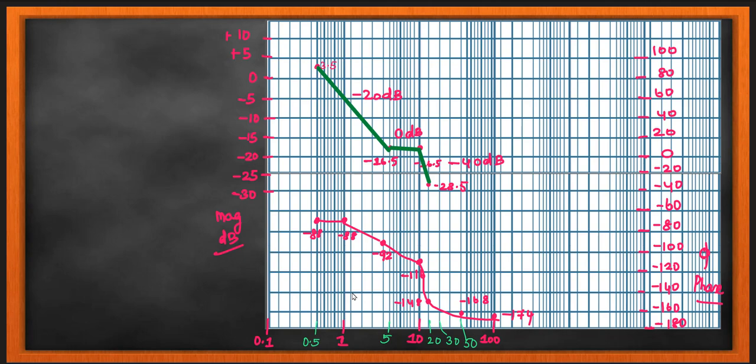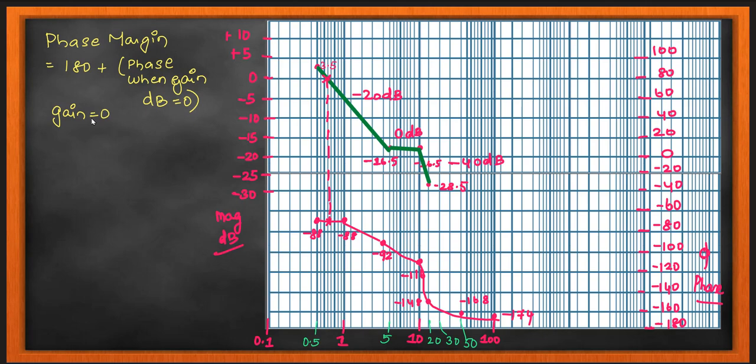I have plotted it, and then I am drawing a connecting line. For the phase, you don't have to have a sharp connecting line. Your line can be as smooth as possible because the slopes are curving slopes. You don't have to have a sharp slope as in the magnitude. For magnitude, you have 20, 0, and minus 20 dB per decade slopes that define it, so we have to draw with that scale. For phase, because we have many points, it comes in a curve shape. But yes, this is how you draw in the exam.